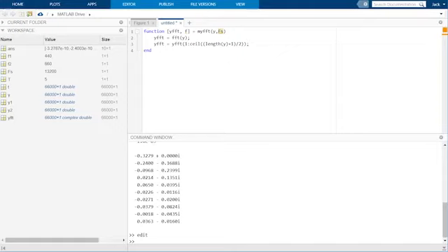As we will see in the next section, the so-called Nyquist theorem tells us that if the sampling frequency of a discrete time signal is fs, the maximum frequency representable in that signal is fs divided by 2. Thus, the frequencies we can extract from our signal y range from 0 to fs divided by 2. The IFFT will assume we use cosines with uniformly spaced frequencies in this range.